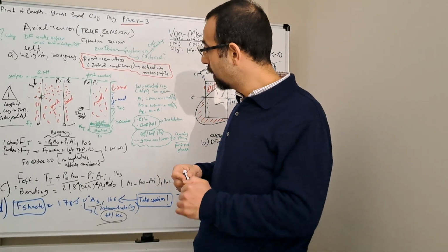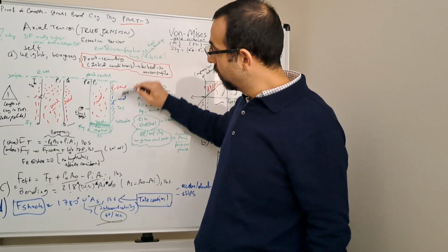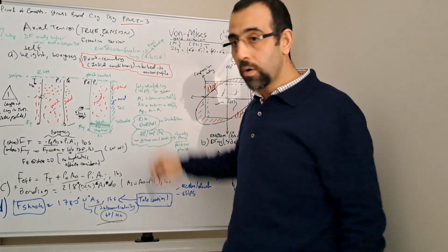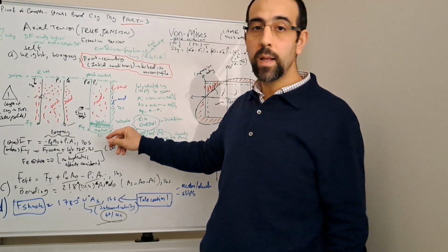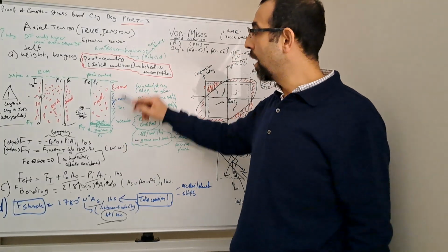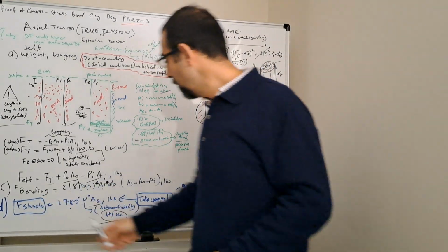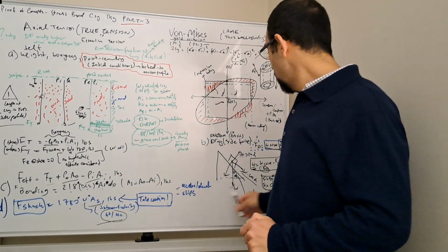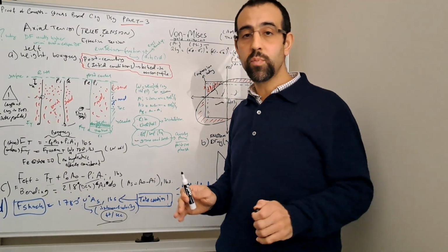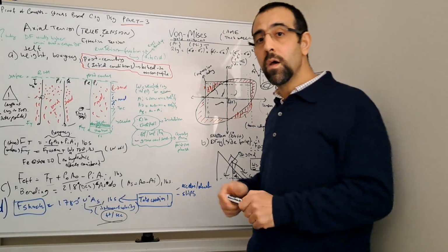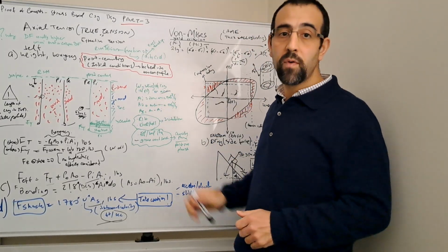You will calculate your internal pressure and external pressure, with the outer area and the inner area of your casing, and accordingly you will work out your true tension at the shoe. That true tension at the shoe and true tension at the surface, taking into account bending, shock load depending on you, and also friction, gives you a locked-in tension profile. For the next phases, for all the load cases, your locked-in tension profile will be the basis.